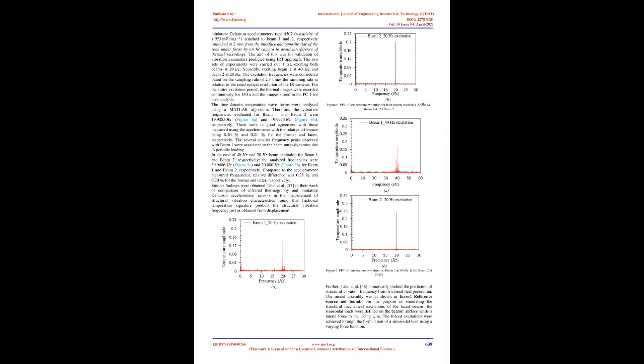Machud et al. 28 studied the existing relationship of vibration with temperature increase on detection of rolling bearing degradation using infrared thermography. The authors inferred that temperature increases with increase in vibration magnitudes. Figure 4. Evolution of the temperature of the bearing cap according to the vibratory level 28.